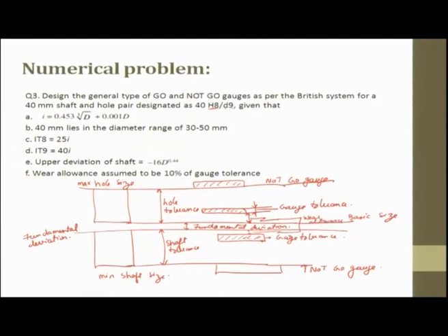This is the minimum hole size, and this will be the maximum shaft size. Okay. So, this is the pictorial representation of whatever we have understood till now.